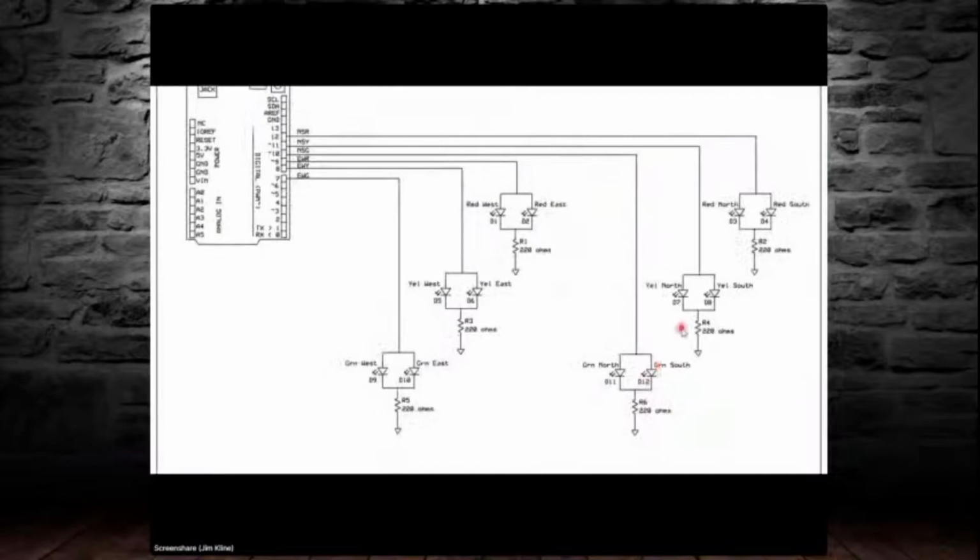Before we start converting the pseudocode into a sketch, there is a certain amount of preliminary setup work that needs to be done. We discussed the 6 pins that the Arduino will be using to illuminate the 6 different LEDs on the traffic light. I know that there are actually 12 LEDs, but the 6 pins are activating pairs of LEDs. Earlier, we indicated that it was important to provide an easily recognizable label that can be used to identify the 6 pin numbers on the Arduino, rather than trying to remember actual pin numbers. In addition, the 6 pins need to be designated as output pins.